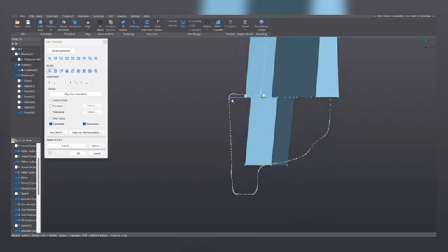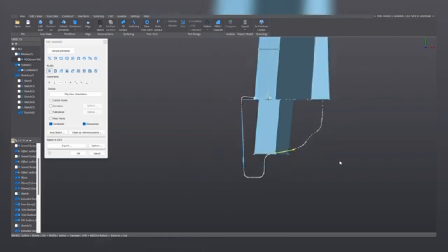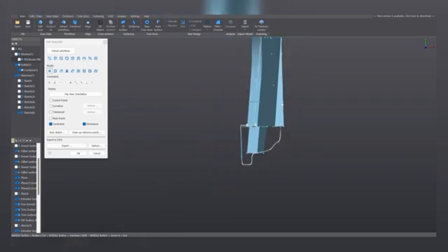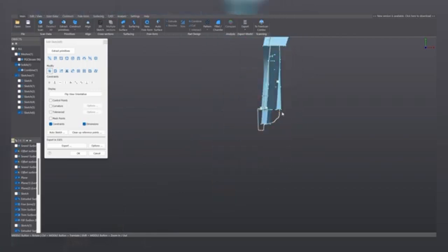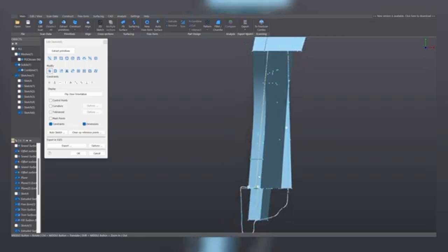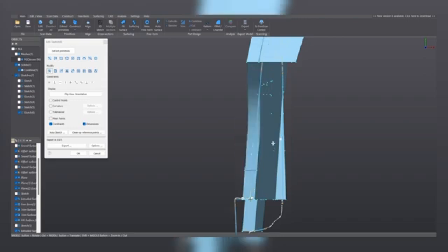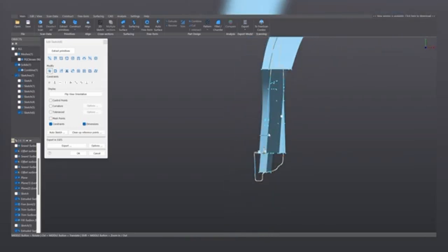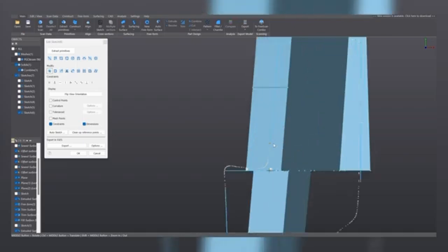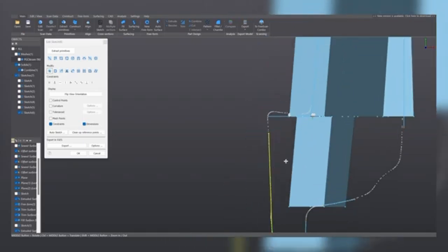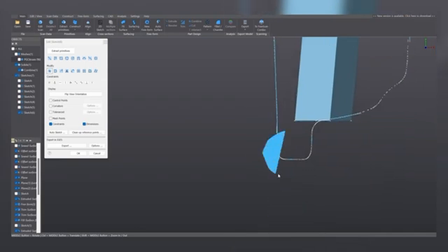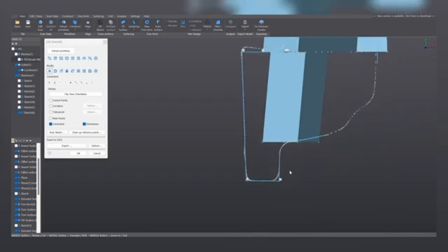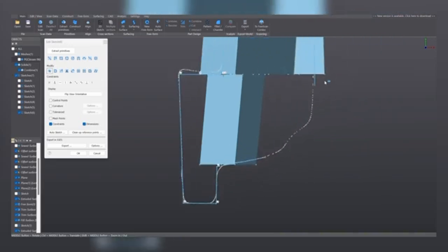I'm going to make a horizontal line here, and let's best fit lines here and there. Actually, yeah, this is a line, perfect. And let's do the same with all this long line here. This looks quite good. Let's select more points. That's it. Okay, and now let's close the sketch. With the Control key, remember, you can connect two endpoints easily.